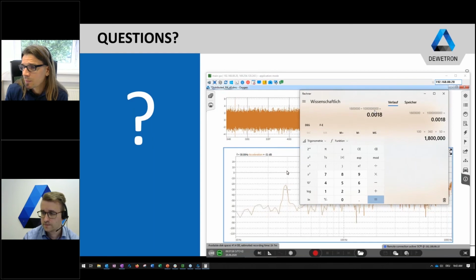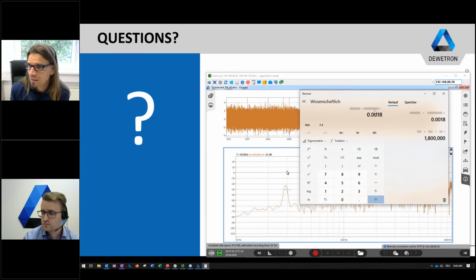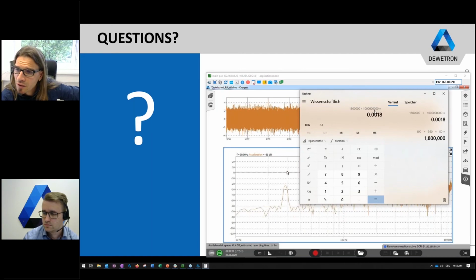Okay. So absolute time accuracy of plus minus 100 nanoseconds, which causes a phase error of approximately 0.02 degree of 50 Hertz fundamental frequency. Okay, thank you for that.